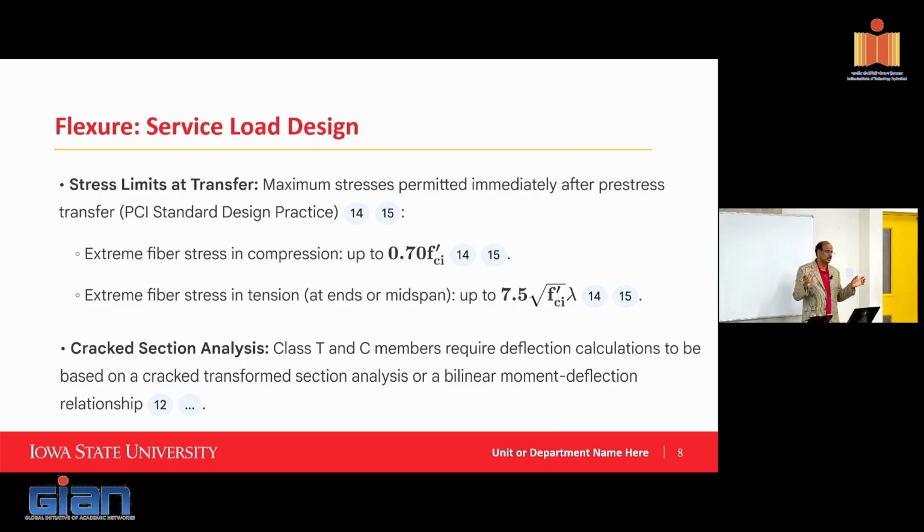A good example would be they may anchor the prestressing strands at the end of the beam where they may have concerns. In between it will be unbonded. They may have an access point to cut that strand and release the prestressing. So let's say this is a beam, and they have concern that it's too long until it gets to the support, and it's supported in multiple locations.